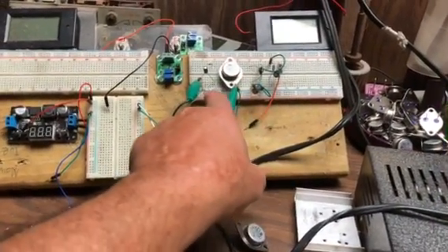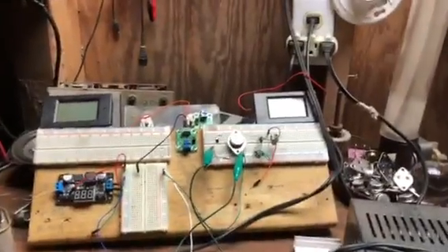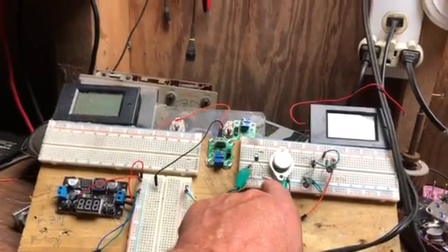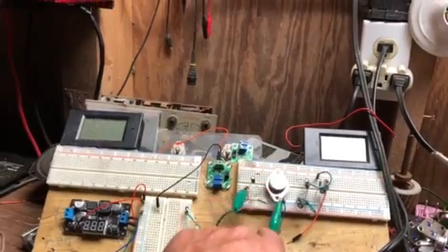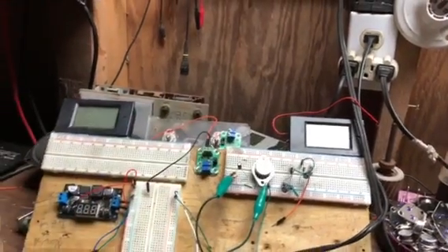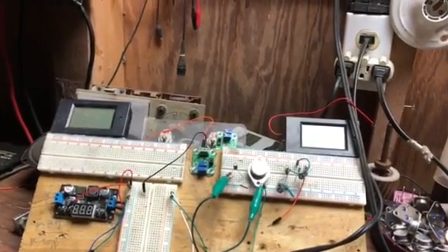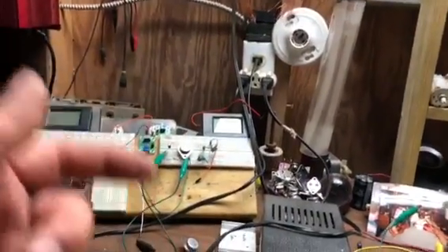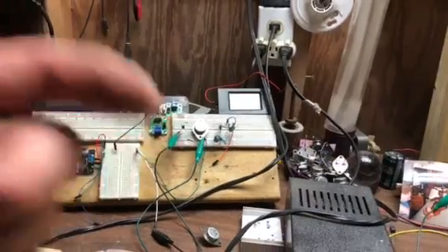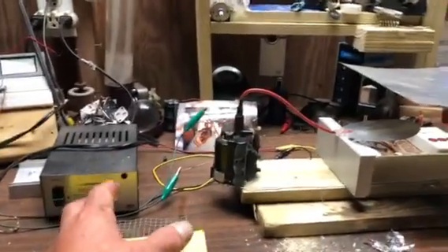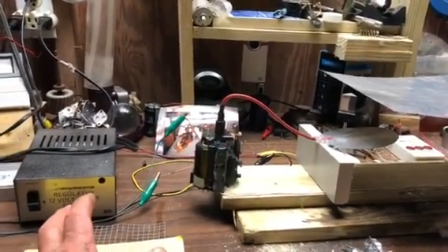And I figured out how to slow down the burning up of all my 2N3055s as I went, after where the base is connected. Not only do I have a resistor, I have a capacitor in there along with one more resistor, which isn't doing anything, but it's there on the back end. You need something there, because if you touch this with your finger, it burns your finger. Not so much by temperature, because it does that, but it also burns by the switching on and off. And that's what we're dealing with, switching on and off 12 volts, 60 watts, so that's some good power there.